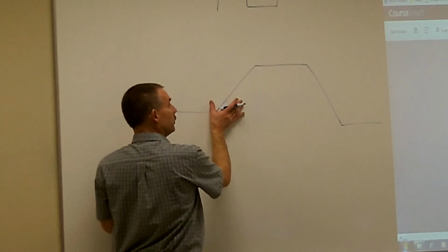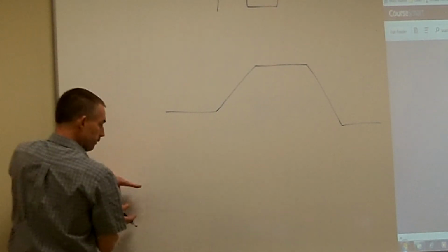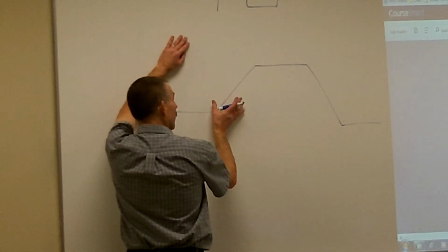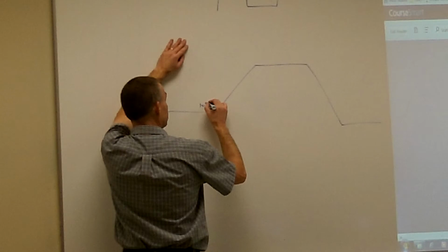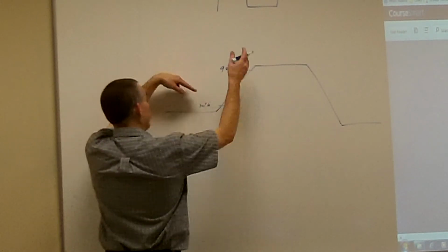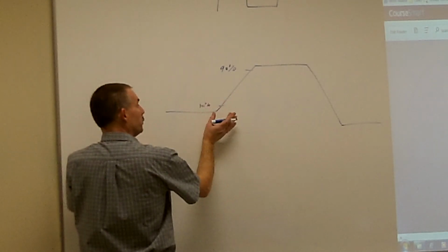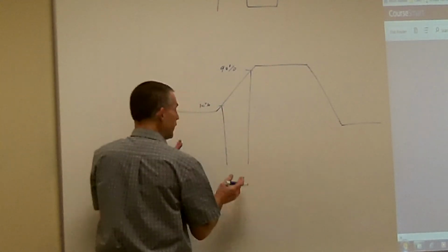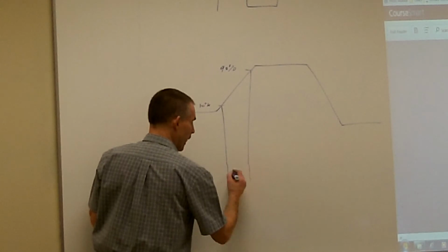So we like to know what that is. This is what we call our propagation delay. Just like I said, we have this clock pulse that's coming in, and at the same time it's synchronizing our data that's coming in. On these clock pulses, there's a range here. We're going to go 10% and 90% of our maximum value. So if it's a 5 volt signal, it'd be 90% down and 10% above. Those are two spots that we mark on our rise time. And then we draw a line down there, and we can actually measure the amount of time that it took for that signal to rise.